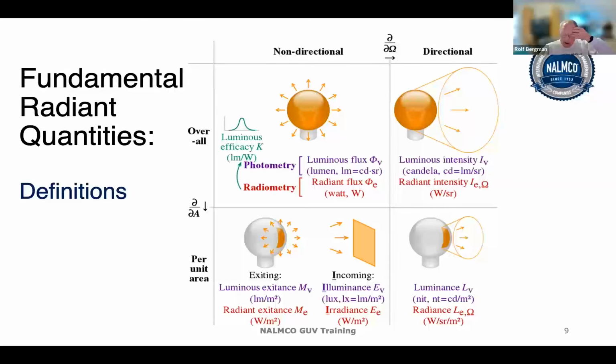If it's light, then this is called the illuminance. It's measured in lux, or foot-candles, which is the English equivalent. But the radiant power is going to be in units of watts per area. So say watts per meter squared, or milliwatts per centimeter squared, or microwatts per centimeter squared, depending on how the units are expressed. So for now, that's what we're concerned with.